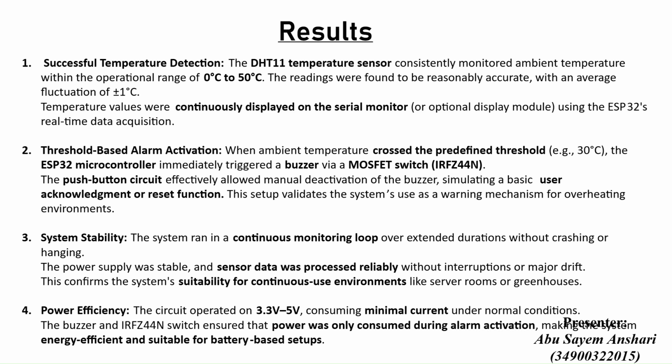Fourth part is power efficiency. The circuit operates on 3.3 volts to 5 volts, consuming minimal current under normal conditions. The buzzer and IRFZ44N switch ensure that power is only consumed during alarm activation, making the system energy efficient and suitable for battery-based setups.